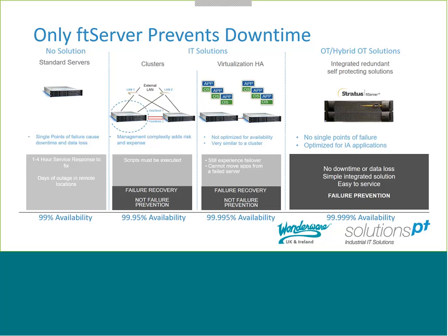If slice A fails, and it's in the middle of writing data to a historian or something, because that bottom slice is just powering on through, riding out that failure, you don't lose what we call in-flight data. So that data isn't corrupt or lost, potentially like you get in the other solutions.